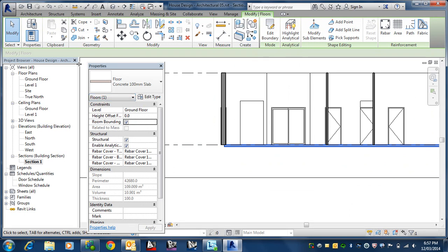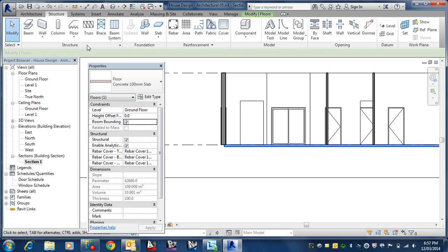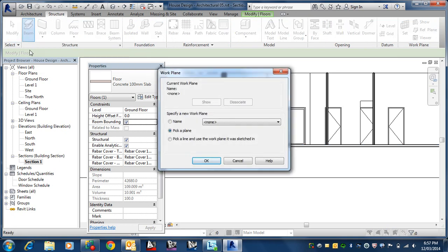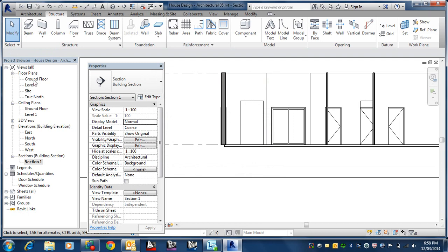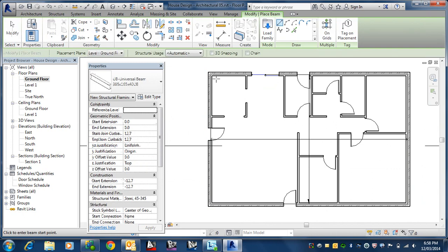Okay, now we need to bring in the beams. So, structure, what is the beams? Column, beam, there you go. Beam, alright. Okay, let's cancel that. Can't do a beam here, of course. Let's go back to ground. Alright, let's go back to beam. Alright, so what we want here is a 350 by 470 beam, rectangular beam. So let's do that.